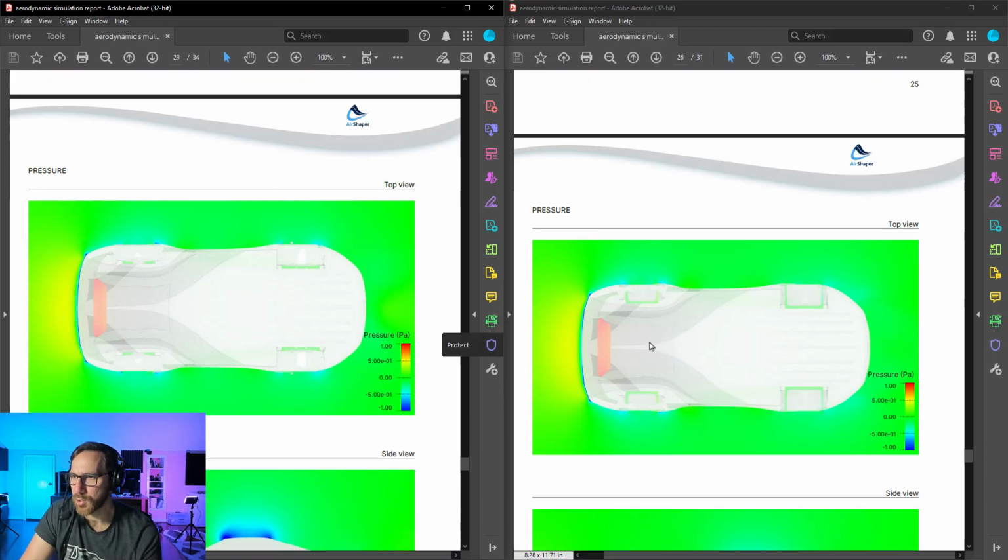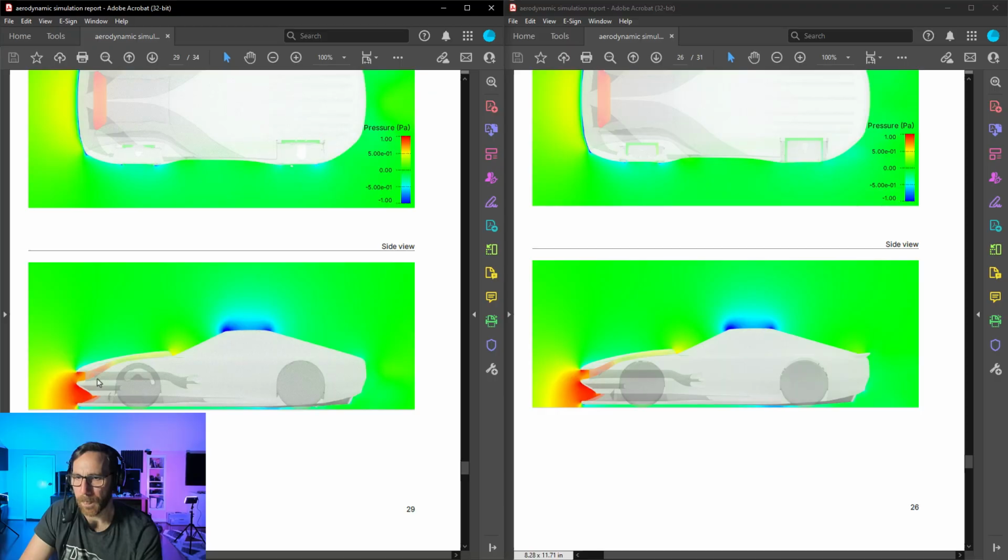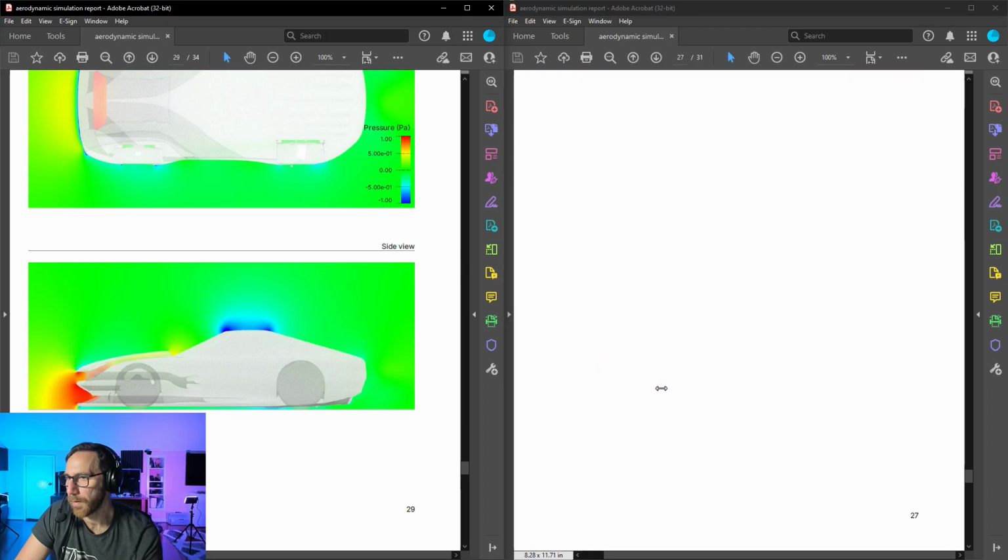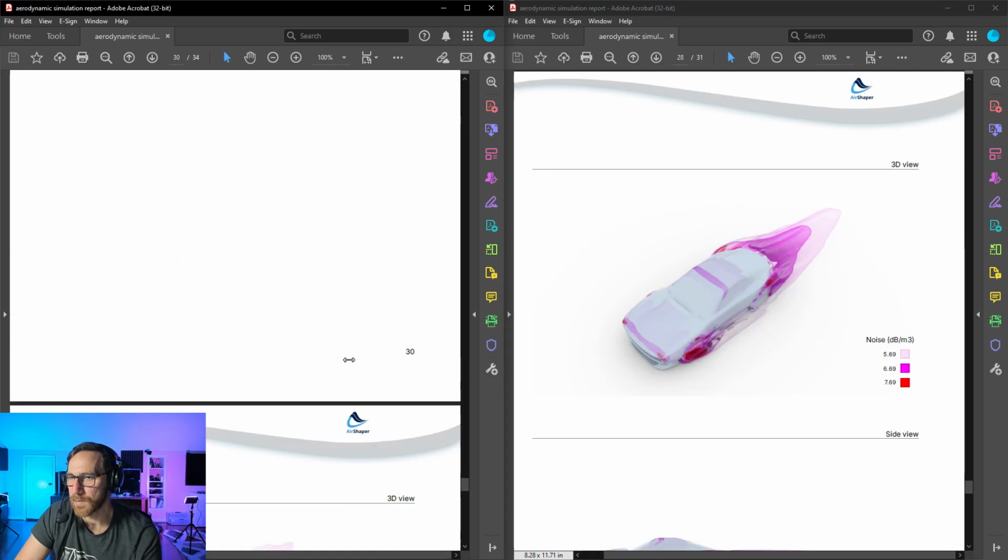And then when we look at the pressure, again, we've got high pressure at the entry of it, and then it's getting lower. It's still yellow right here, but it's getting lower as it goes back. Because this section plot is right through the middle of the vehicle, the only one that we're seeing this for is inside of that cowl hood, and we're not seeing the same sort of plot going through the other ducting, but there we go.